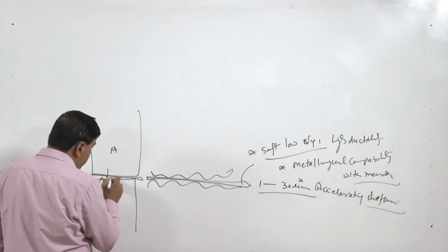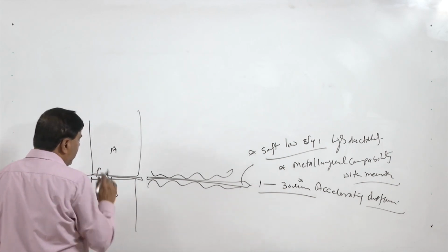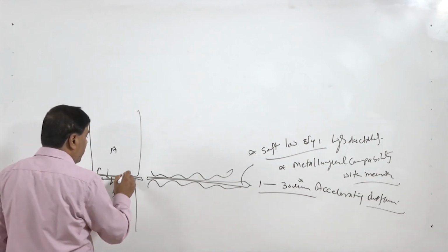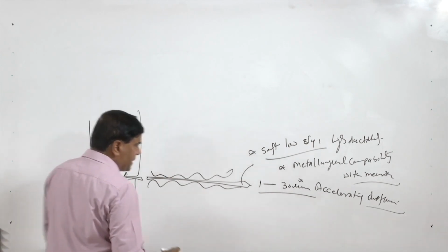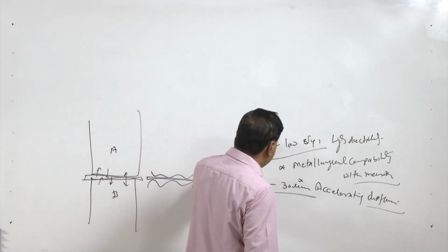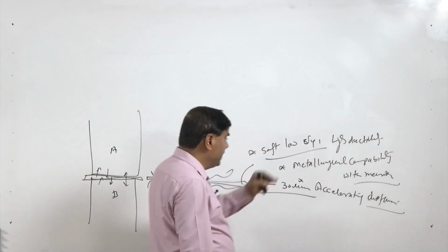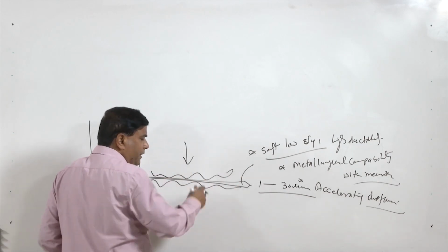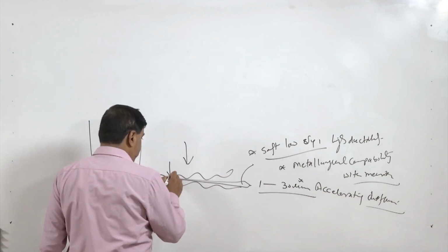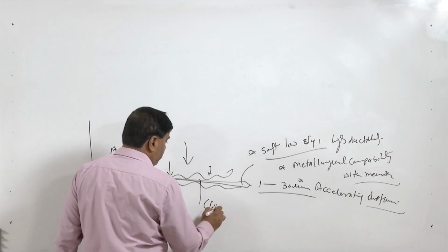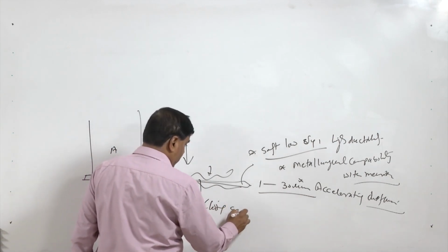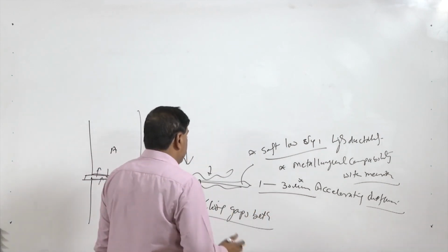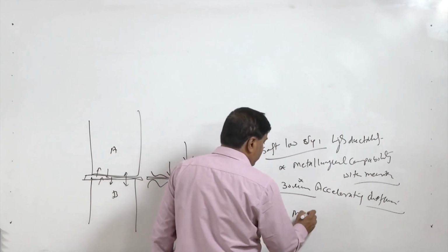Another is that the presence of this interlayer can help in accelerating the diffusion across the interface, so the bond is formed quickly. Third is that the soft, low yield strength, high ductility interlayer under the pressure will get deformed following the path of the peaks and valleys, and so close the gaps between the peaks and valleys, increasing the metal to metal contact.